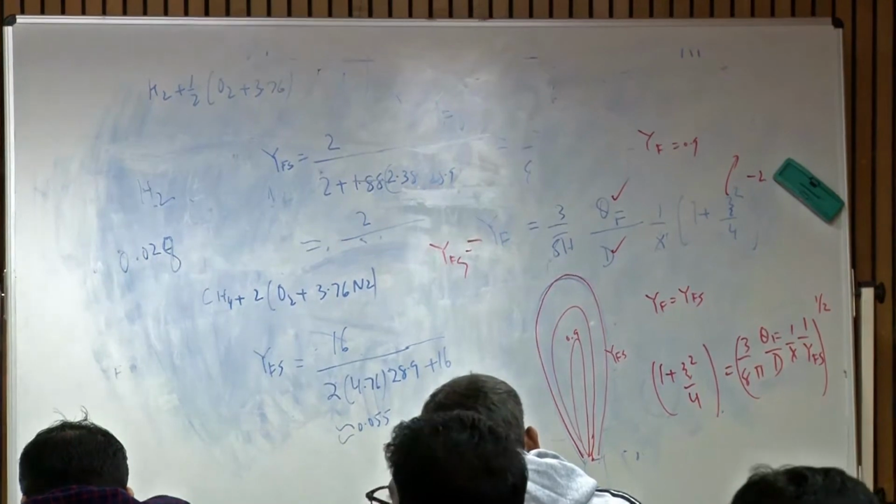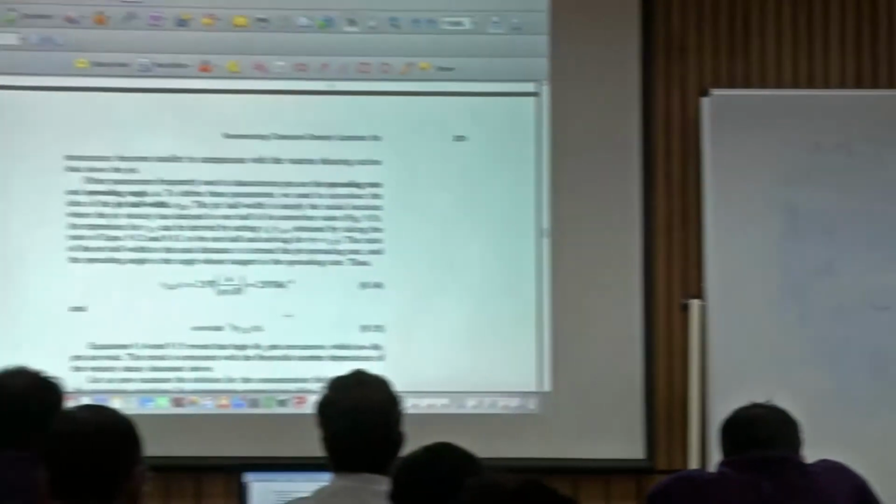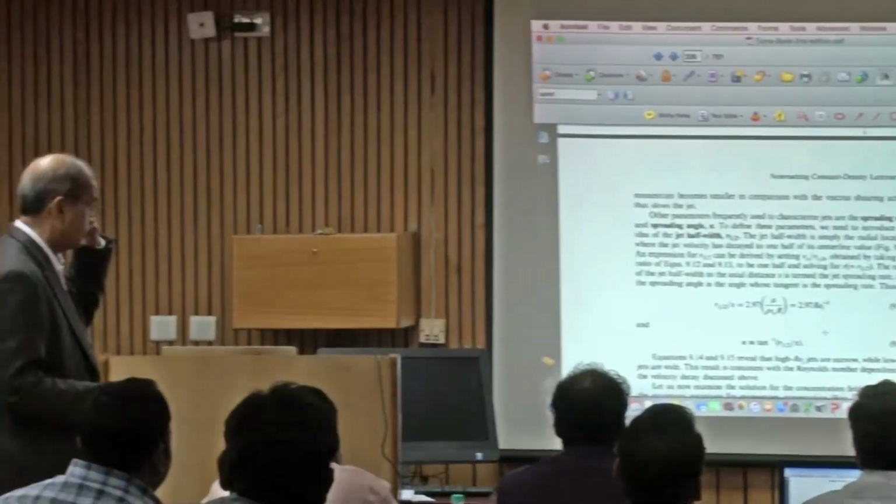Here we also have to discuss a very interesting approximation called the flame sheet approximation. We are assuming that fuel and oxygen come to this flame and the combustion occurs instantaneously. In the limit, that means the Damköhler number is infinity.